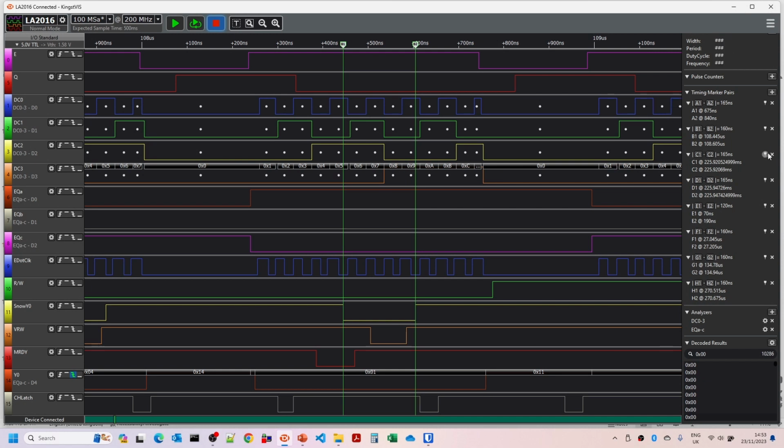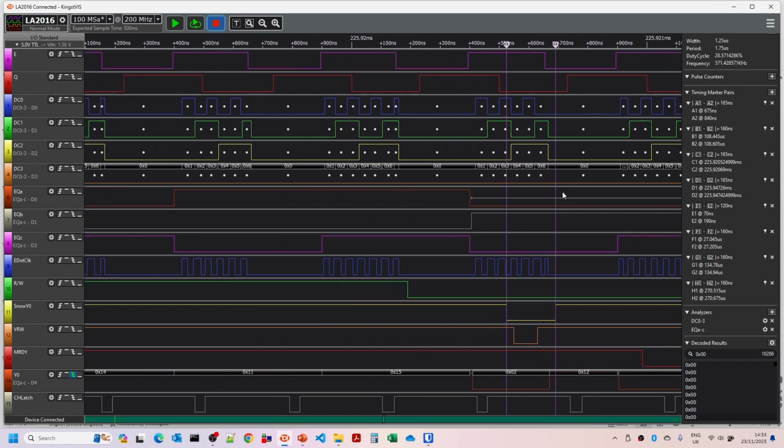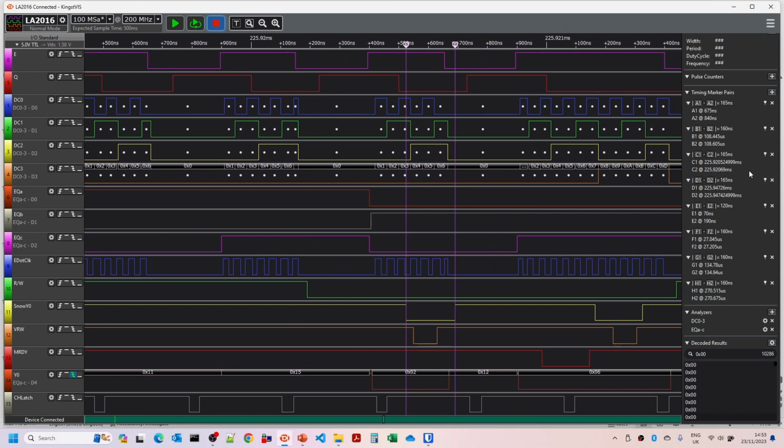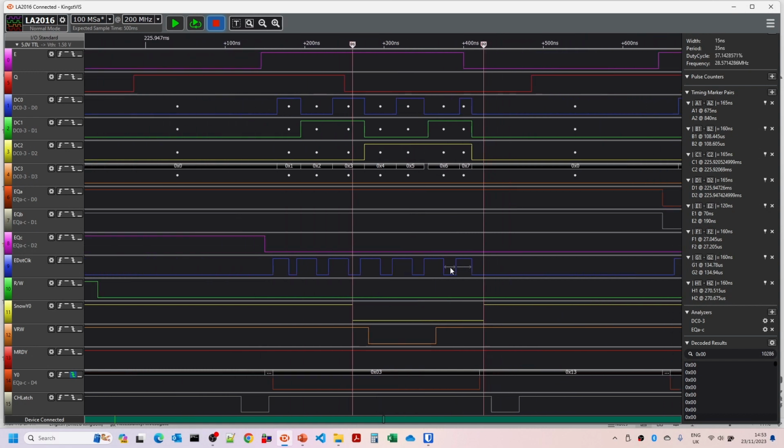So that's the B. If we look at C, again similarly, this C1 is for 02, so this doesn't have a memory ready signal here. So this one is just unaltered, so you can see here the E signal there is 260 nanoseconds, but again it fits neatly between these two here. If we look at D, so this should be 3.